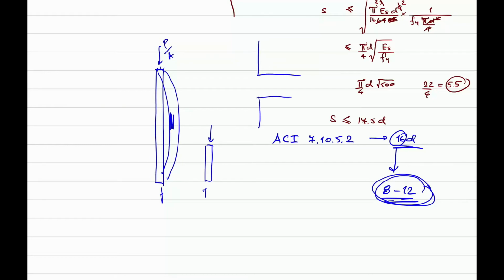You expect high strain in this plastic hinge zone, right? Because the plastic moment is mobilized over here, a large compressive strain is expected here. So you will also need to provide some extra, and the spacing will be reduced due to that fact. Okay, so not far.